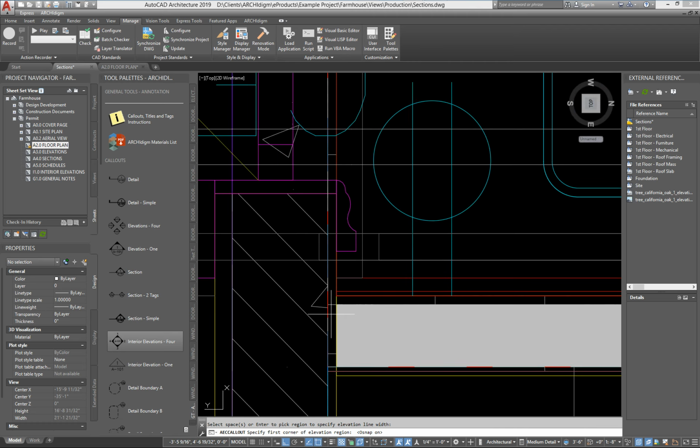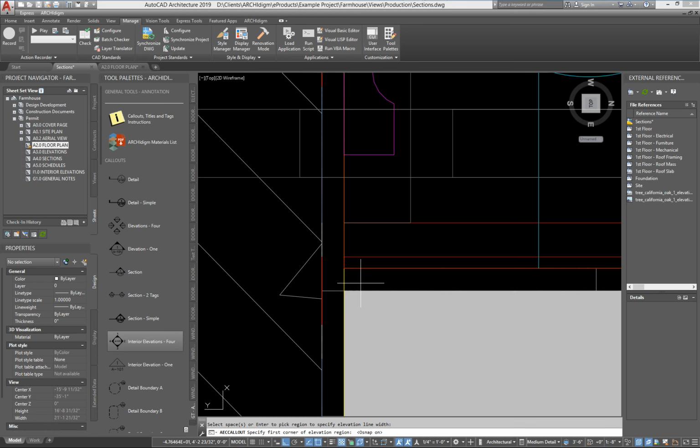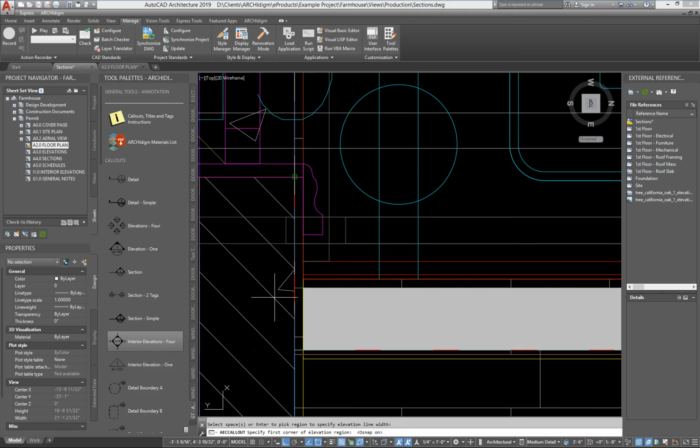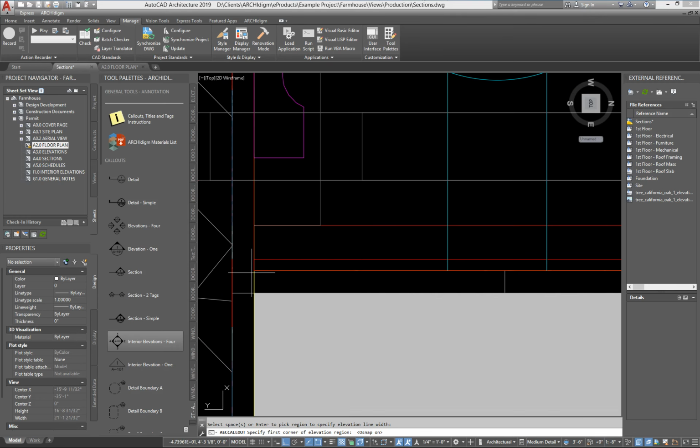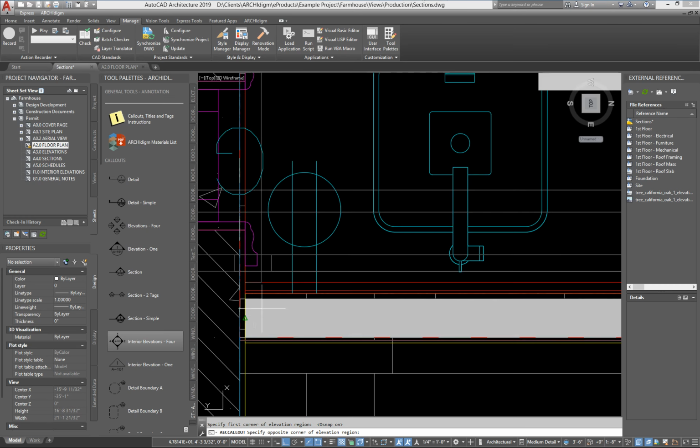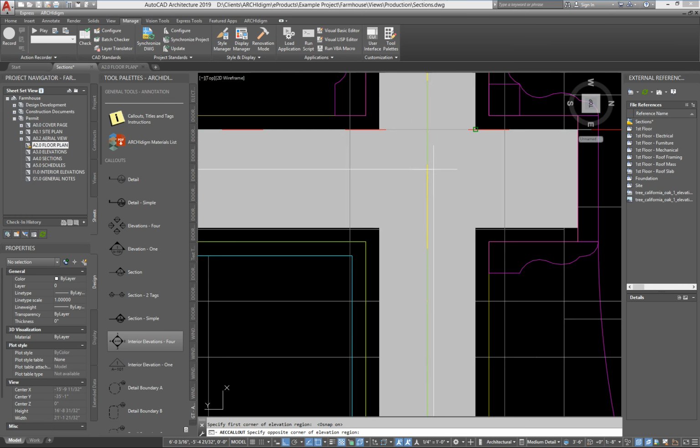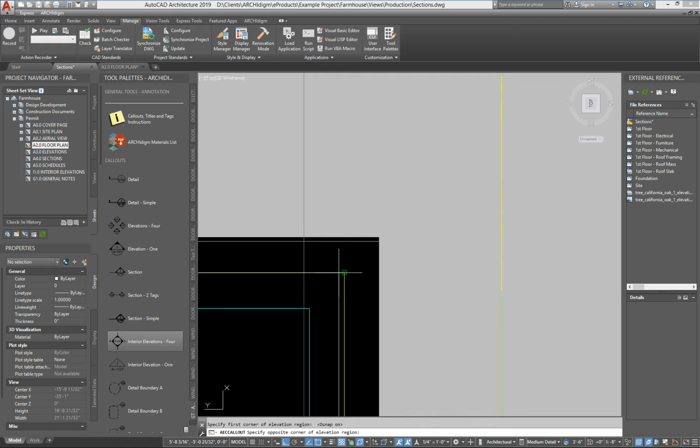And if you zoom down into a corner and you use ARCHIdigm's walls, all of our walls have materials. So for example, this is a residential interior wall. This is a residential exterior wall. And I can see that this is the sheetrock here. This is the ½ inch. So I'm going to go ½ inch into the wall in this corner. And then in the opposite corner, I can see this is a ½ inch. Here's the edge of the sheetrock. I'm going to go a ½ inch past.